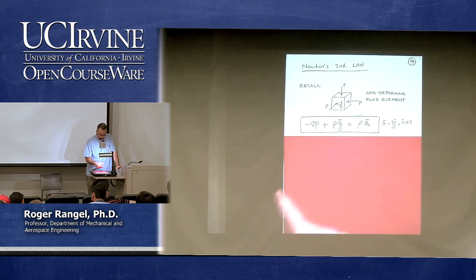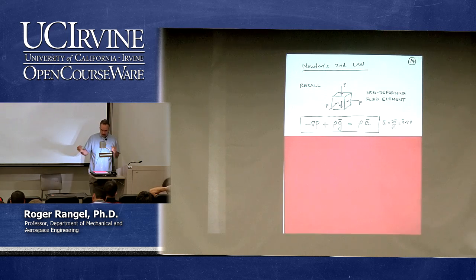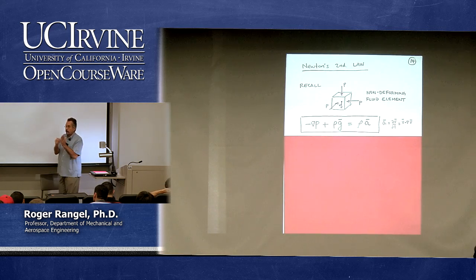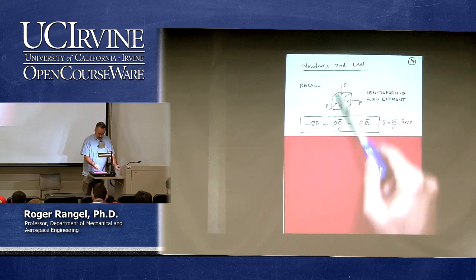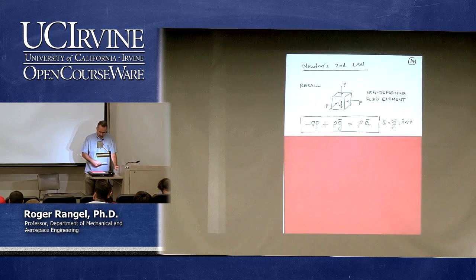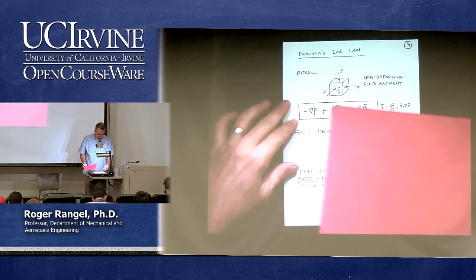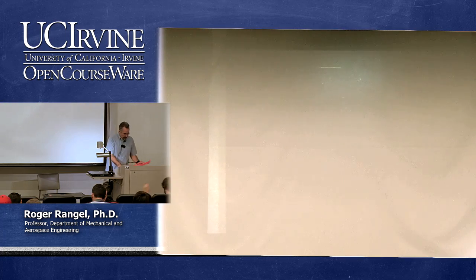So that's my element. There are the pressure forces. By definition, the pressure forces are perpendicular to the surface and point into the surface. So for those three sides, those are the pressures. And then you can see also the weight there. So those are all my forces. That's, of course, when we left viscous forces out.